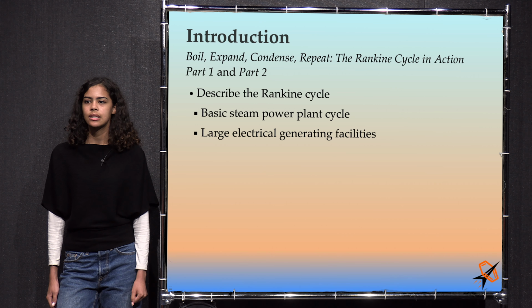First of all, as we did in the Entropy Made Me Do It, pumps, nozzles, and the other second law shenanigans video, we see that the work rate over m dot is delta H hat, and that's going to be V hat delta P, which is why we looked up V hat of the liquid. So we have 0.001 cubic meters per kilogram times the delta P, which is 8,000 kilopascals minus 9.1118 kilopascals, that comes out to 8.067 kilojoules per kilogram.